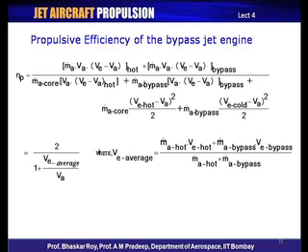And this is exactly what a bypass jet engine essentially aims to achieve, and this shows up in the form of SFC. And that is why one tends to have a bypass engine, even if it is a low bypass engine, as it is used, we have seen between Mach 1 and Mach 2, just a little bit of bypass, and this is why it is done.